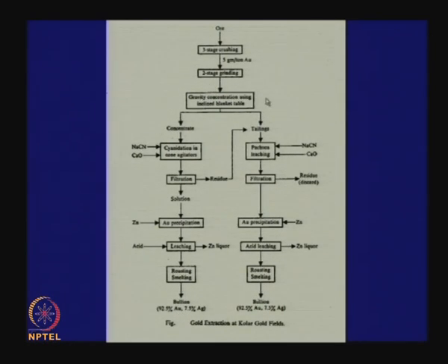Now, the tailings: here we are segregating gold and silver, and the tailings would go through sodium cyanide leaching again, precipitate gold by zinc, acid leaching, and then we are left with a bullion again, 92.5% gold and silver, which means nothing is allowed to go waste. You go through the concentrate, and the residue tailings should also be treated in the same manner, but eventually we do produce gold and silver, mostly gold and a little bit of silver.